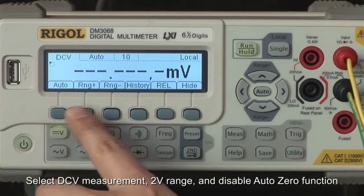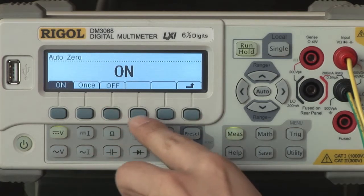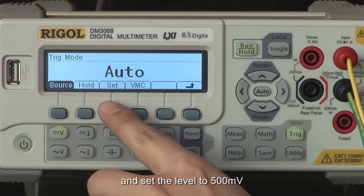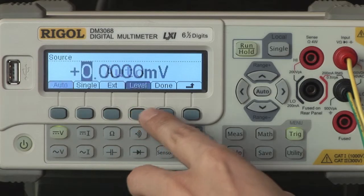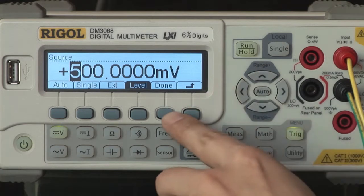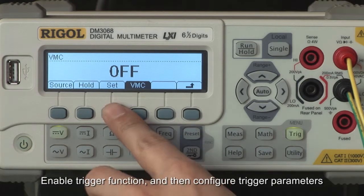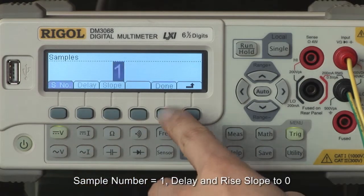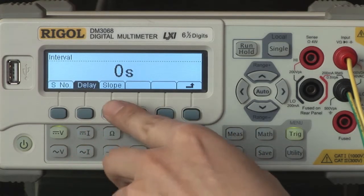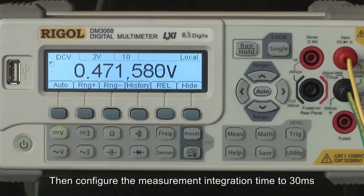Select DC volts measurement, 2 volt range, and disable the auto zero function. Change the trigger type to level trigger, and set the level to 500 millivolts. Now enable the trigger function, and then configure the trigger parameters: sample number to 1, delay and rise slope to 0. Then configure the measurement integration time to 30 milliseconds.